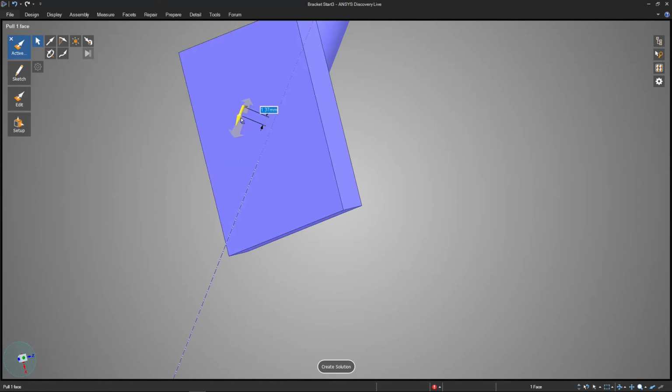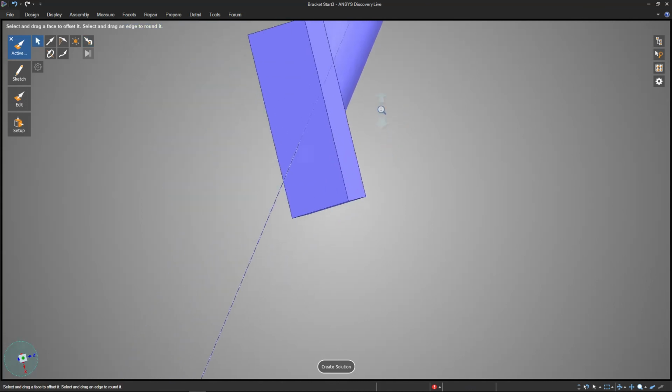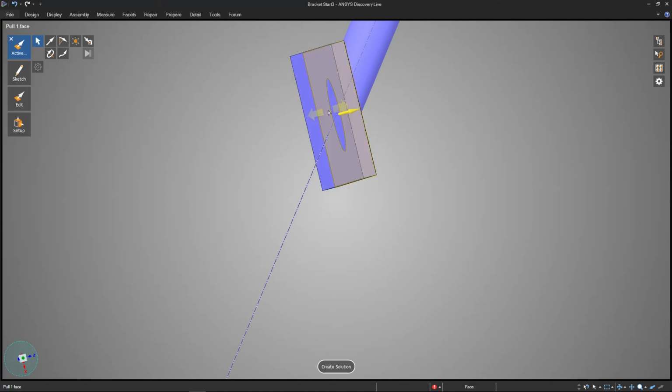And it does a nice job there of mending the face as we go, but if we go too far, then it starts to think I want to subtract. So I'm going to again use the up to tool, so it goes straight to the face but no further, and it just cleanly makes that nice and solid. If I check the interior geometry, you can see scrolling my mouse wheel there, there's nothing tricky hiding inside of there. It just blends them all together nicely as one shape.